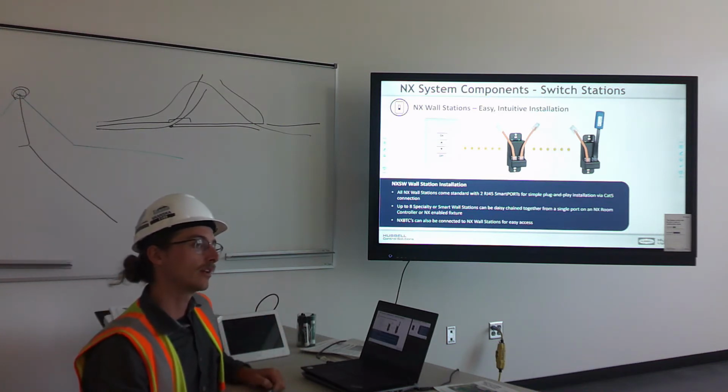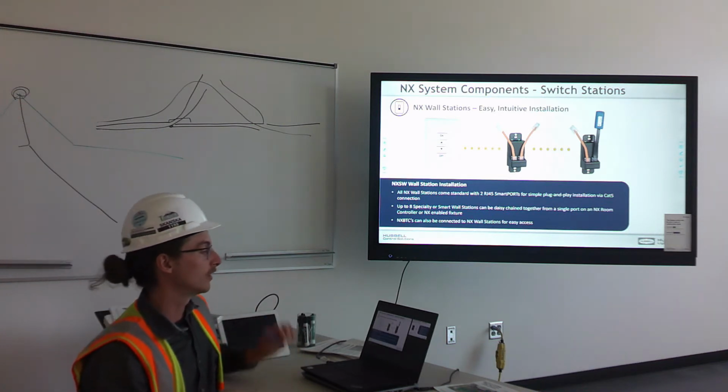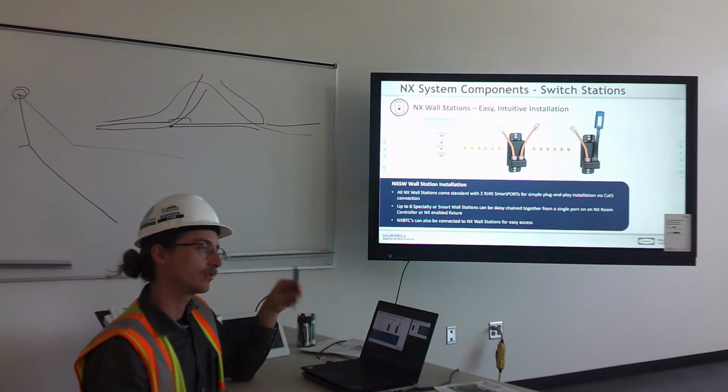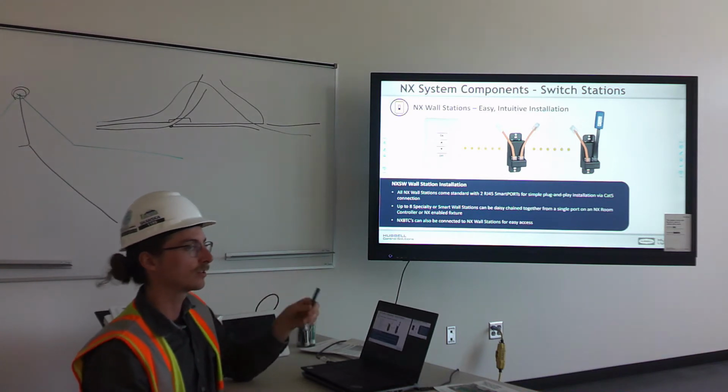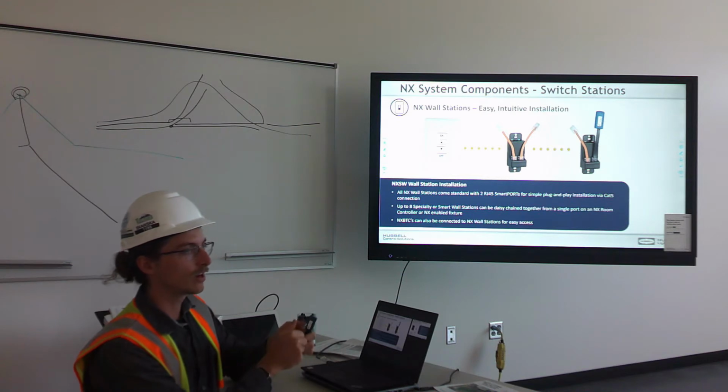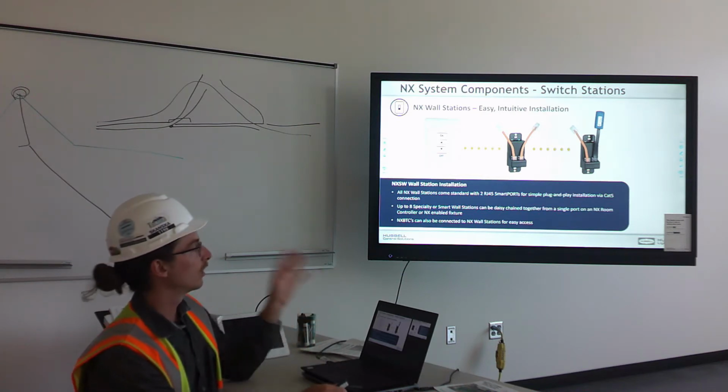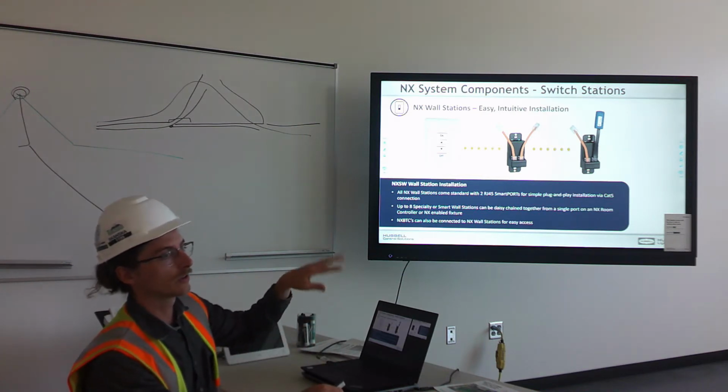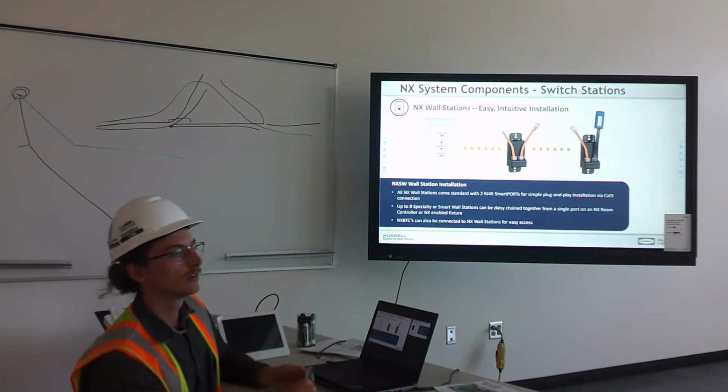The only way to do that during the day would be to either plug in your Bluetooth into the switch. You could take it out of the wall, plug the Bluetooth in, go into the override and shut off the relays, or go in through the area controller, find the relays and shut them off.